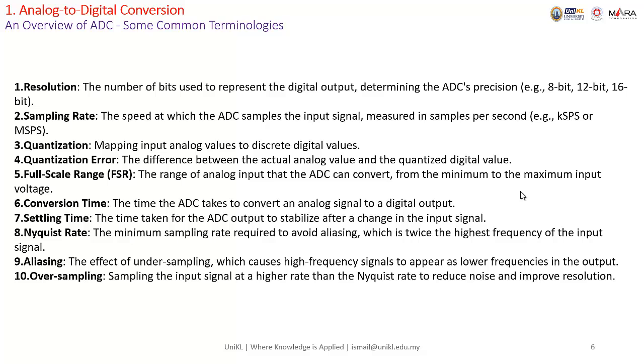And then oversampling. In signal processing, normally we will sample at higher rates. For example, assume we have a signal of 1 kilohertz, that is the maximum frequency. Then we filter it, say 1 decade above, at 10 kilohertz, then we sample at 20 kilohertz.